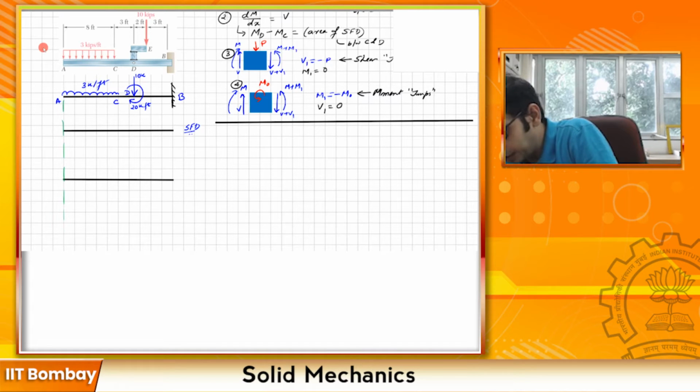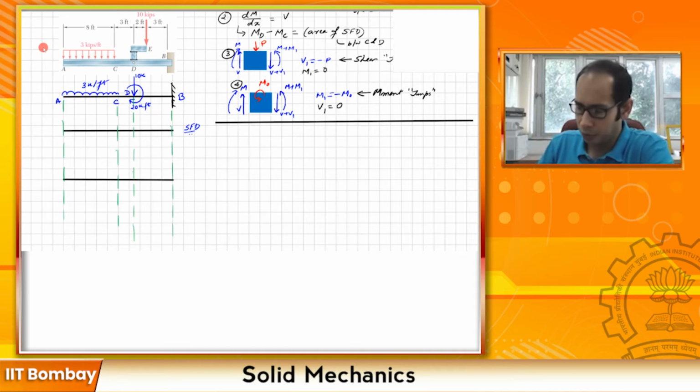One guideline at A, wherever you have discontinuities or the load ends or begins. So I have these A, B, C and D. Focusing on the shear force diagram, this is my A, this is C, this is my point D, and lastly this point B.